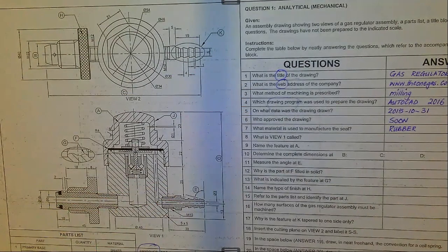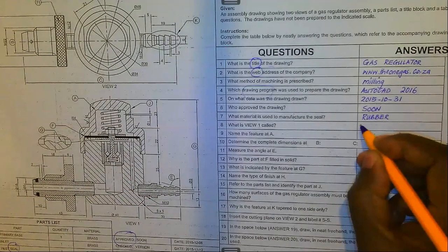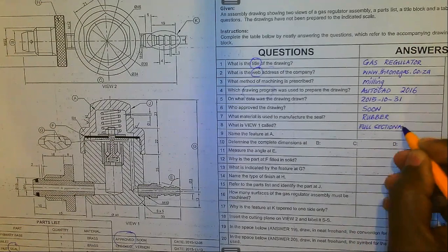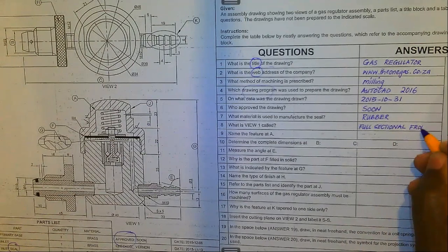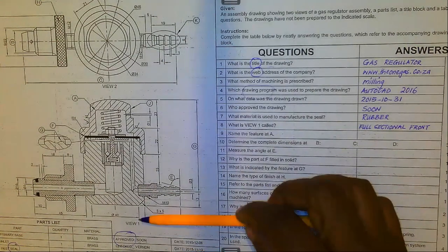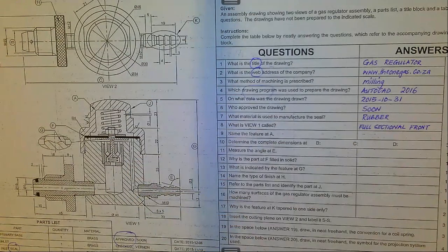So we are going to write here full sectional. View, it's already there, so that would suffice if you simply state full sectional front. So that is the view. Remember the view that you see just below, if there are 2 views, one on top of each other, and you see these in paper 2, automatically you know that the one at the top is the top view, and the one below is the front view. With 2 views side by side, one could be the front view, and the other either a left view or a right view. So that also needs to be taken into consideration in terms of understanding this.